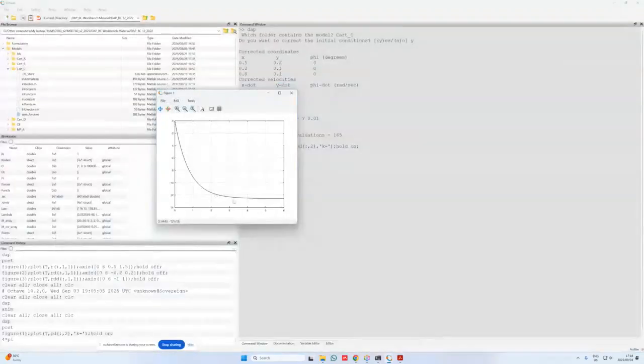So if I compare this to where this curve plateaus at around 4 seconds, it seems that after about 4 seconds, the maximum torque in the system is reached. Sorry, not the maximum torque, but the maximum angular velocity of the system is reached. And that's why I now get a constant value onwards at around minus 12.57 radians per second.